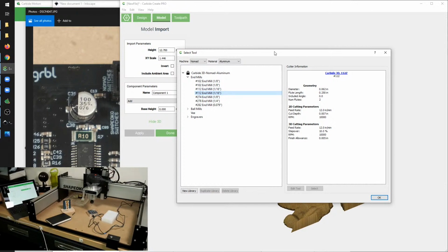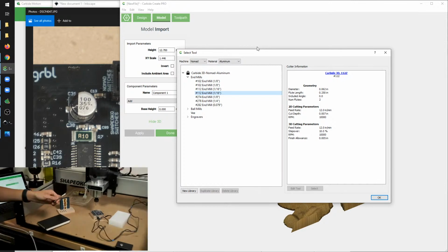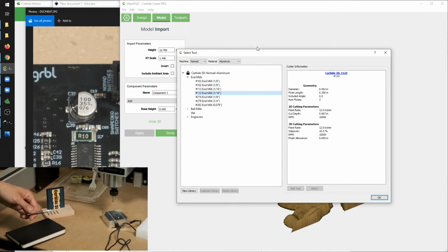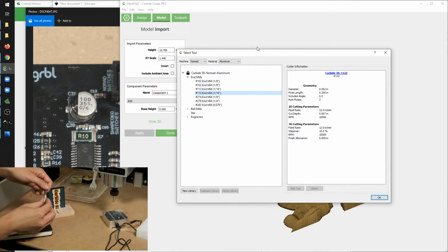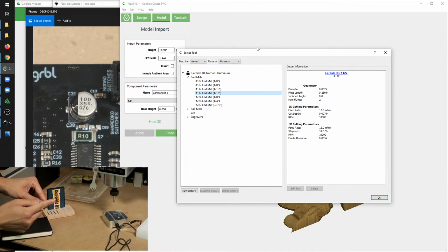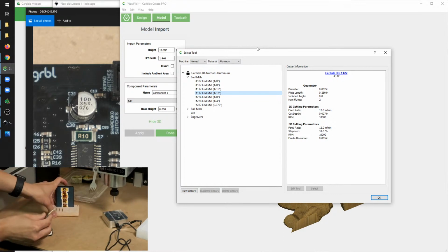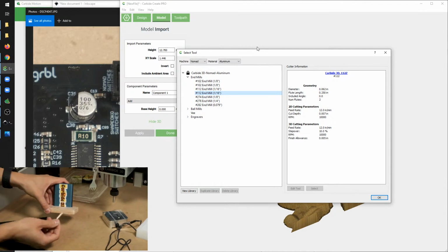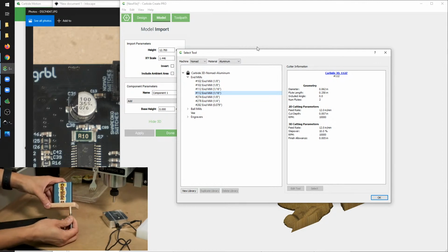Let's see. I think the last question I have is, can you do mild steel on the Nomad? Technically, yes. So the thing about machining is you want your tool, let me focus this. For every revolution of the cutter, you want the cutting flutes to bite into the material a certain amount. So if you go too slow, if you're not able to feed fast enough, you're basically just going to rub the end mill, create dust, create friction, dull the end mill.